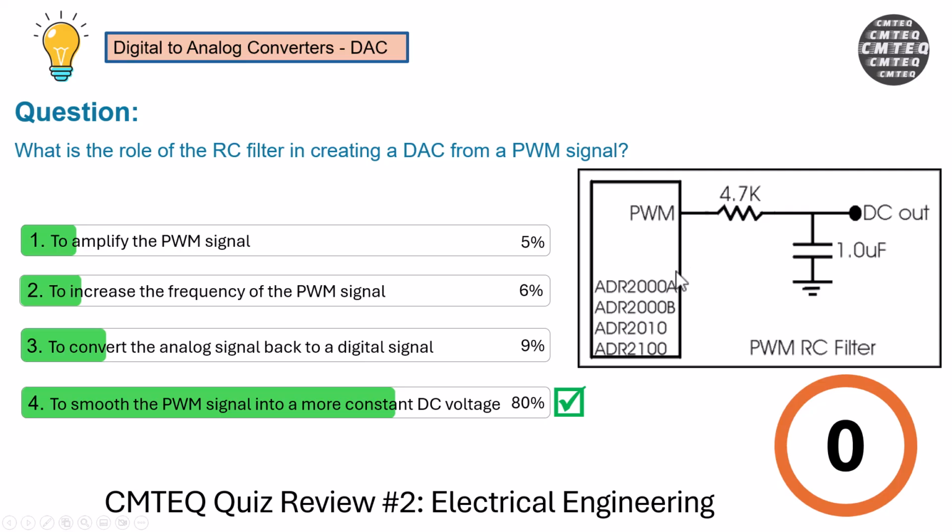But over here, you can change your PWM frequency or resolution or duty cycle to basically just smooth out or control whatever you want on your DAC. So you've got more flexibility in this system. Hence, these are more advantages. Great stuff. Now let's go ahead and move on to the next question.